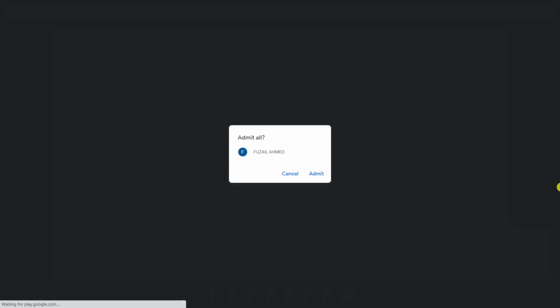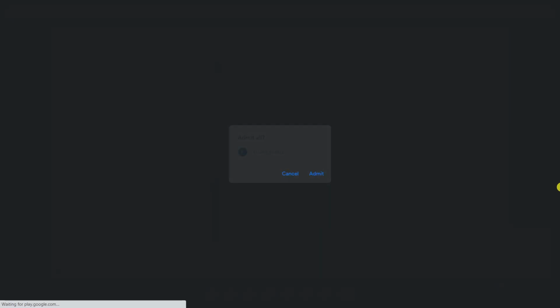What I would do is select the face, the element selection of face, to get the surface of this, say the bottom surface, and select the edge to get the start and the end point.